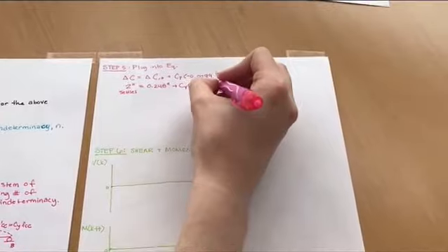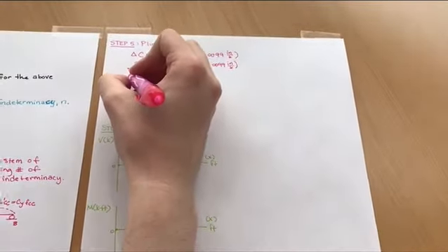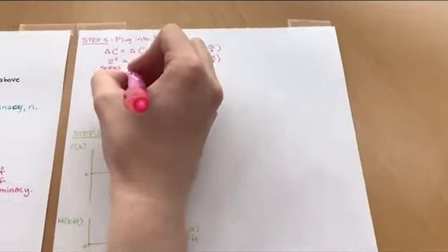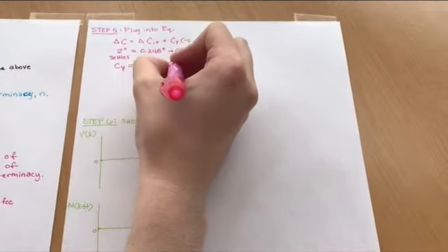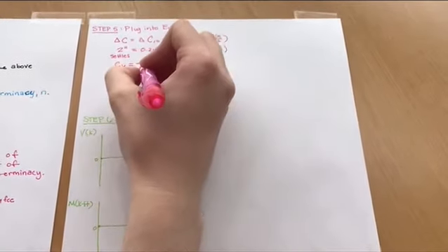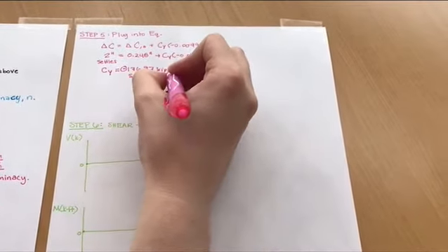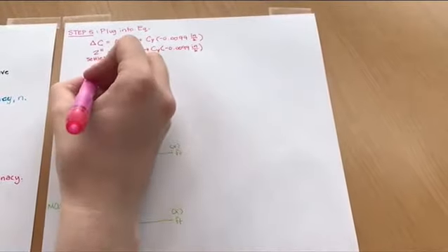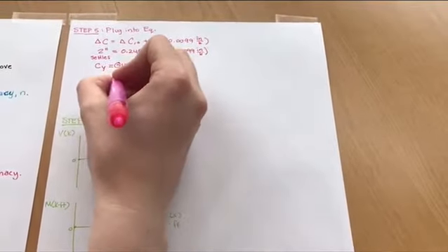It is important to learn this method as it will be used in the field if you do go into structural engineering. An example of this is if you have a complicated structure and you need the reaction of, say, a crane system, if you're designing a building with a crane system, and you need those reactions to put on your structure to account for those loads. It's also, as this example shows, if you have a member that settles in part of it, it will have a great impact on the reactions from that settlement.